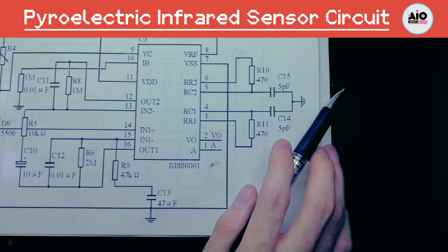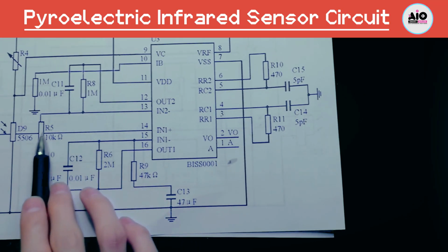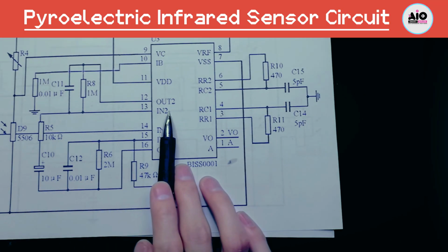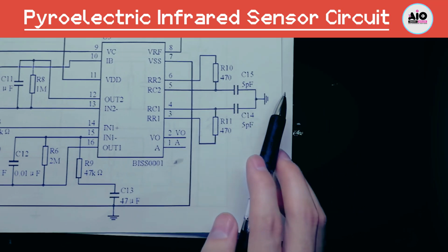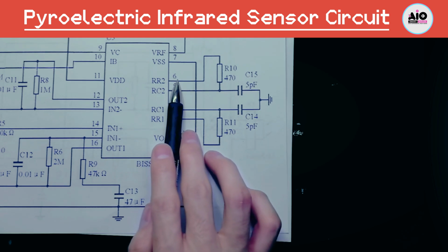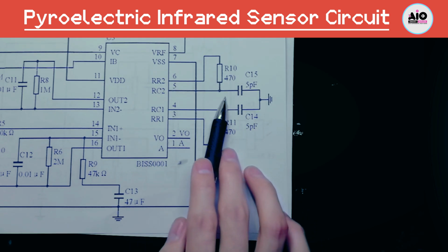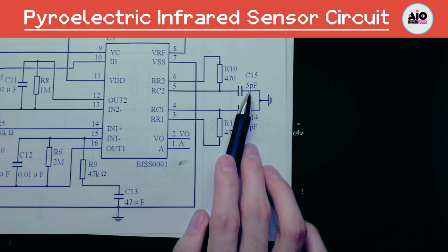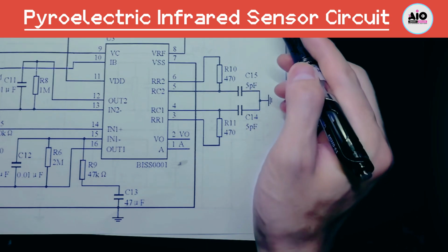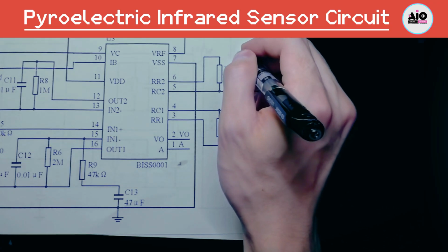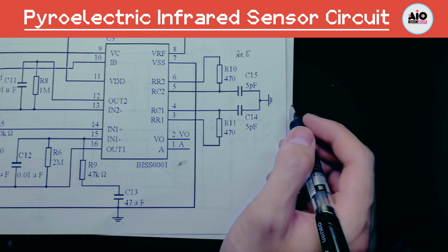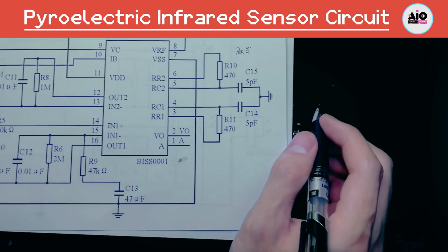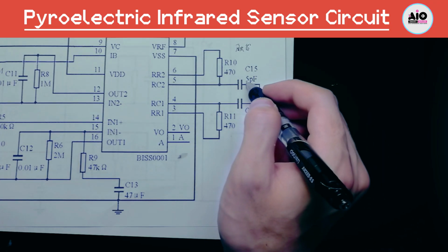When the light is weak at night, the resistance of the photoresistor will become larger. At this time, pin 9 will become a high level, and it will be controlled by the thermal infrared sensor to achieve the purpose of output control. The circuit on the left is the peripheral circuit of these 2 parts. It is the peripheral component part of the amplification part. Then what about the external circuit of pins 4, 5, 6 on the right?